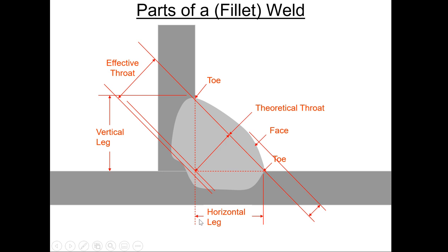These are the typical weld sizes you would get if you were making components, any of the components on the shop floor. Lastly, the reinforcement. The reinforcement represents the bump of the weld on top, and that is how far it sticks up. If this gets too big, it starts to cause issues. It actually starts to cause distortion issues and crush issues, where this material is trying to pull on itself when the welds get too big. Multiple layers of thin passes is exactly what the order of the day is for TIG welding.